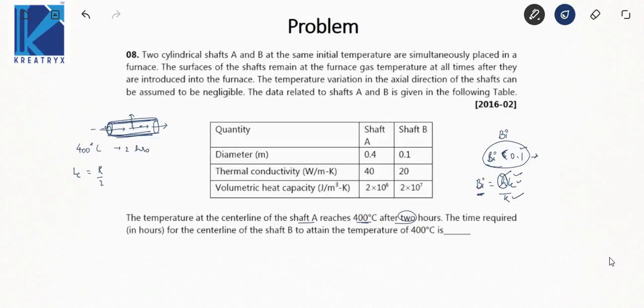Now whenever time comes into the picture and you cannot apply lumped system analysis, you have studied another number, that is Fourier number. What is Fourier number? It is a dimensionless time number. Okay, and it's very important, listen carefully. It comes into the picture when studying conduction that varies over time, when the lumped system analysis approach isn't appropriate.